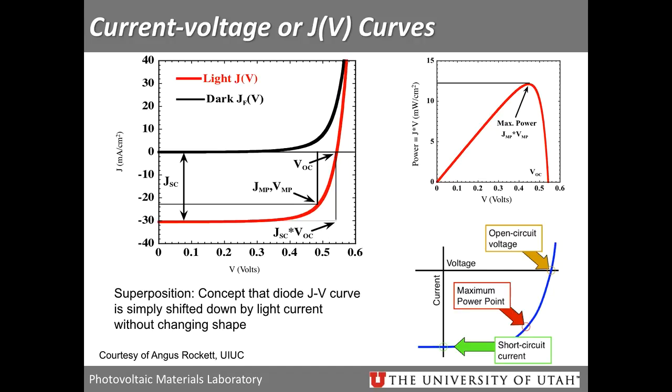So what this is showing here, if you remember the plots that I showed of the maximum current, the maximum current in a solar cell will always be at 0 voltage. It's a short circuit current. The maximum extractable voltage will always be at an open circuit voltage when there's no current flowing. So your maximum power point is a function of what your JV curve looks like. And so you're essentially trying to find your ideal power point, and this is where the resistance of your load comes in. So if the resistance of your load is too low, you won't be able to extract voltage.